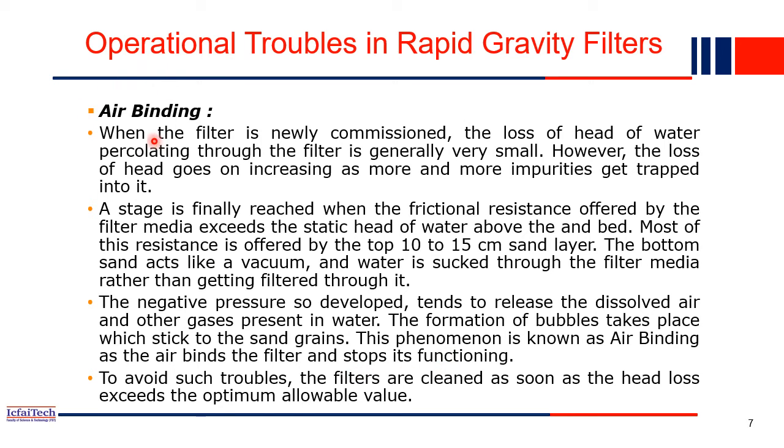Now you understand what air binding is. Let me draw it quickly here. You have different layers, right? Initially you have the sand layer at the top and the gravel layer at the bottom. When water passes through this filter medium, the pores in the top layer will be filled up with the impurities present in the water. Those impurities will simply be stuck in the top few layers, whereas the bottom sand layer as well as the gravel layer,